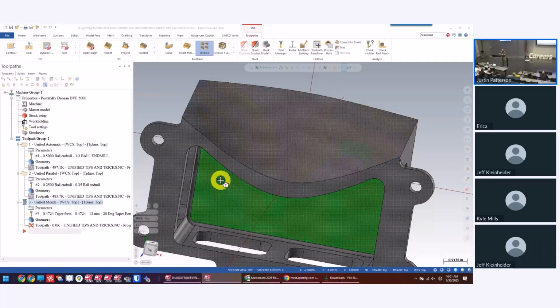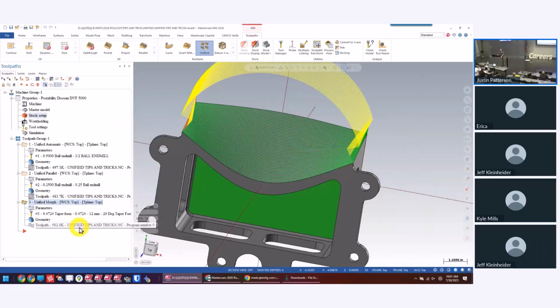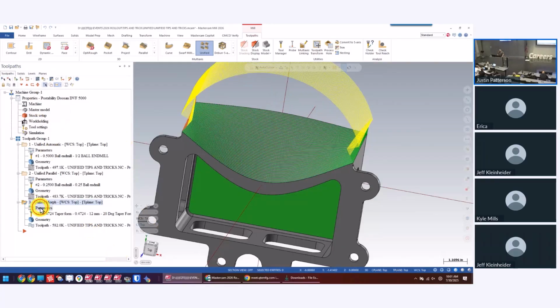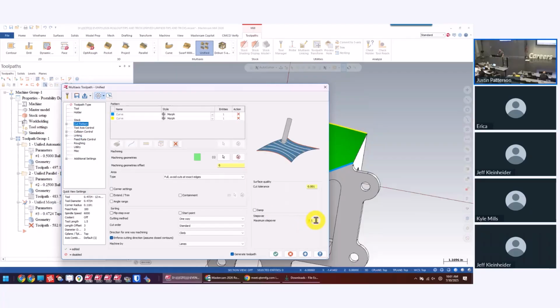Is it cutting what I want, how I want? In this case, yes, it is. It's cutting the surface I want, the direction I want to cut it, okay? So if I can get, come on, mouse, work for me. See, it's starting where I want. It's cutting the wrong direction, but a lot of times I'll fix that at the end, okay? My step over messed up on me, but going here, I guess it's still 100. That's fine. Okay, you could probably do more.